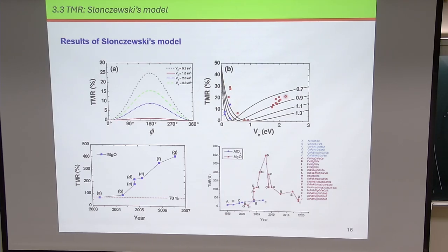So this TMR effect is actually very large, and here is a comparison of TMR for different materials. It depends very much on the character of this barrier. I think the first magnetic tunnel junctions that were built typically used aluminum oxide as a barrier, but aluminum oxide is an amorphous material, so you have a lot of disorder in there, and therefore the effect is not so large.